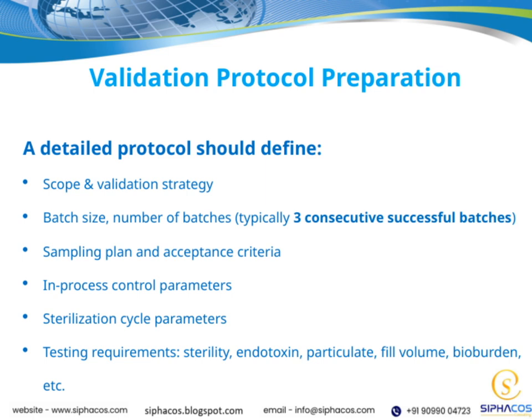Testing requirements form the backbone of validation, covering sterility, endotoxin levels, particulates, fill volume accuracy, bioburden, and other relevant quality attributes. All these elements should be incorporated into your validation protocol, which serves as a comprehensive plan for how validation will be conducted. Remember, preparing a thorough validation protocol is fundamental to the overall quality assurance process. It provides a clear roadmap, ensuring that every step is documented and reproducible, ultimately supporting product safety and efficacy.